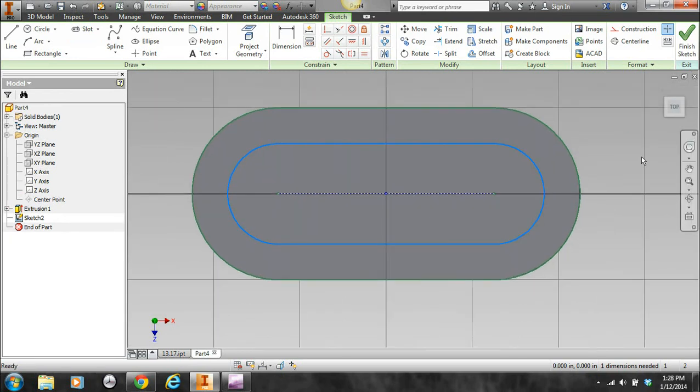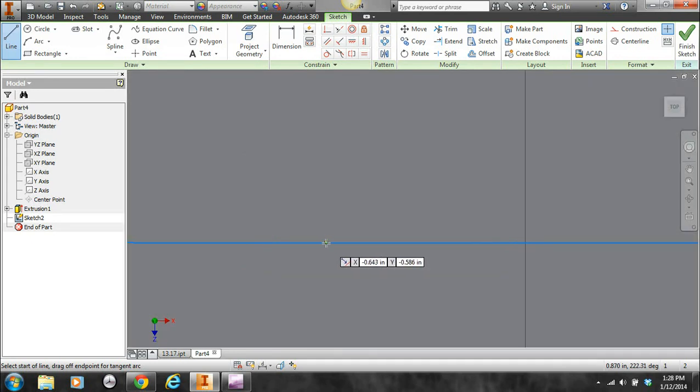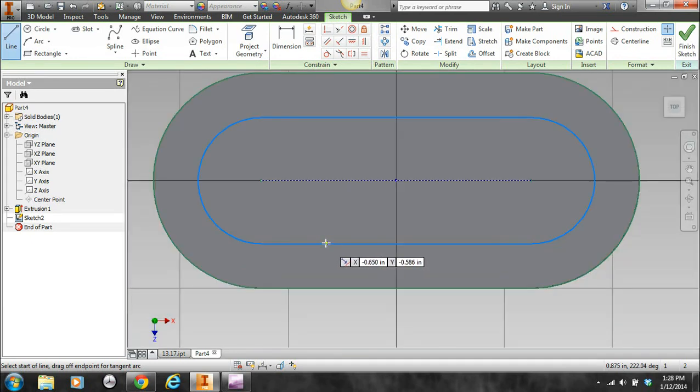Actually, before I do that though, let's go ahead and draw a couple of lines, and I'll just draw a line. And now your crosshair should kind of get near the line and want to snap. Okay, so once you feel that little snap there, you can left click and then pull your line straight down. Notice the perpendicular constraint near my crosshairs, and I'm going to continue until I get to the edge, and I see the perpendicular constraint and it snaps to the edge.